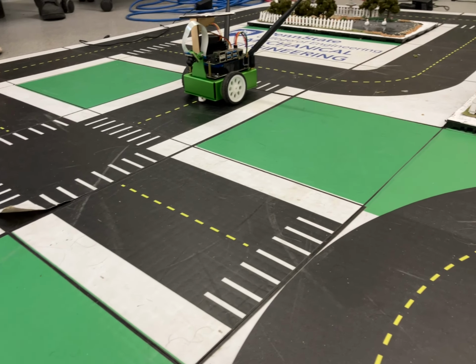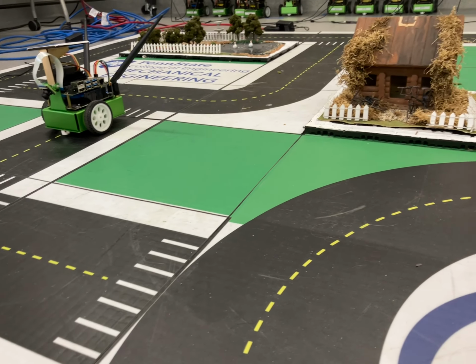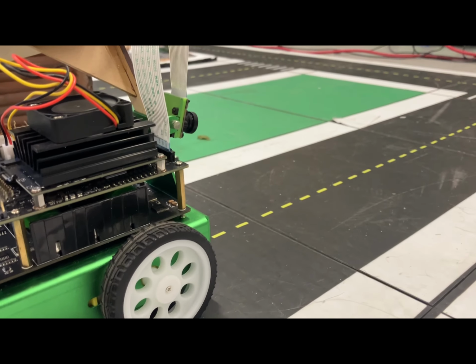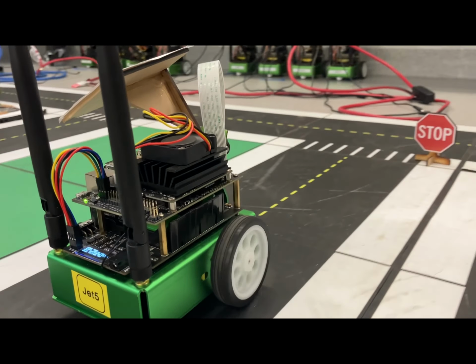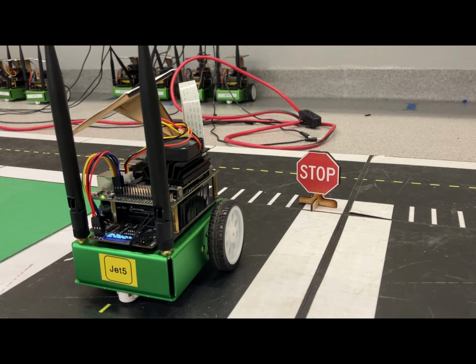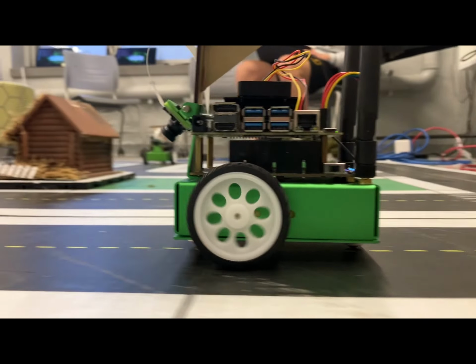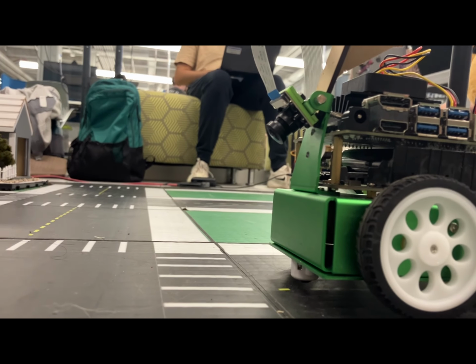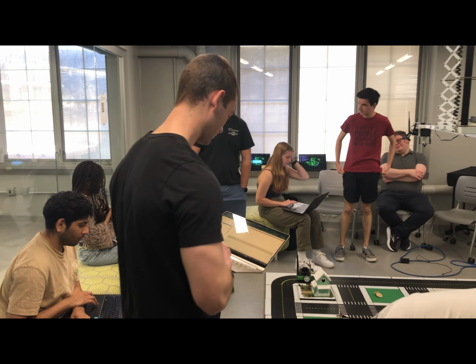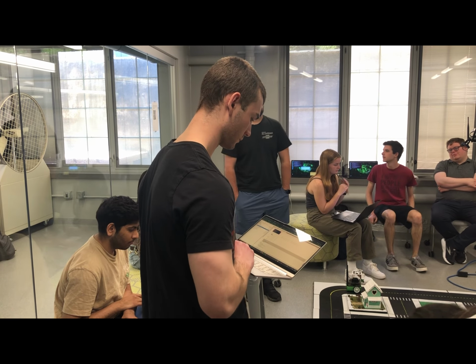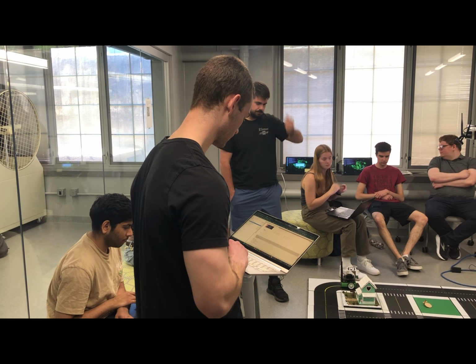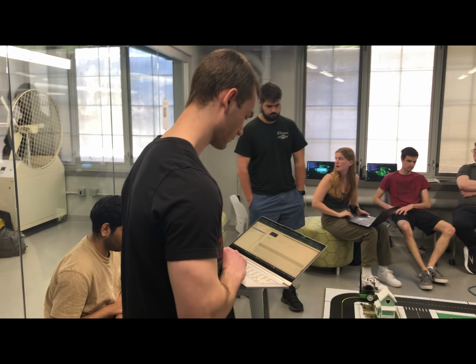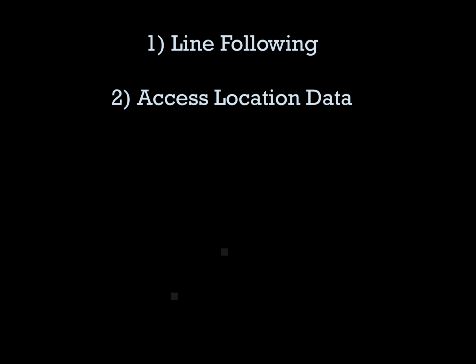For the final project, our team can decide on the extent and the nature of the autonomy that the JetBot has. There are 5 total function choices from the laboratory experiments: kinematics, line following, pattern recognition, April tag recognition with robot-to-robot communication, and pathfinding. Our team must complete at least 2 of these objectives. We chose to program the JetBot to follow lines, determine position, and make turns using kinematics.